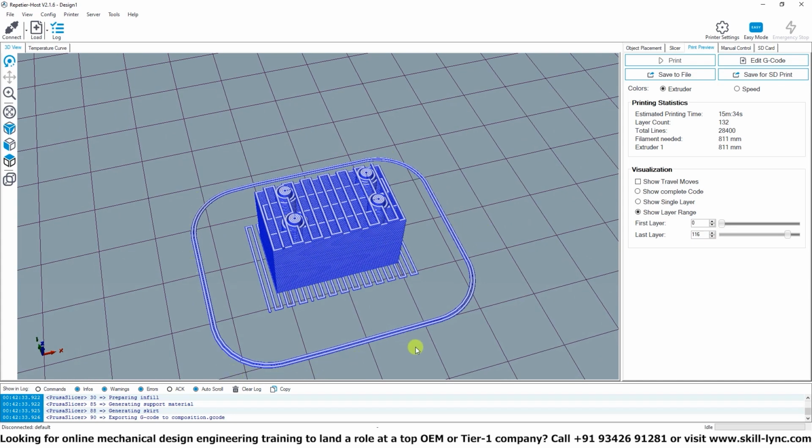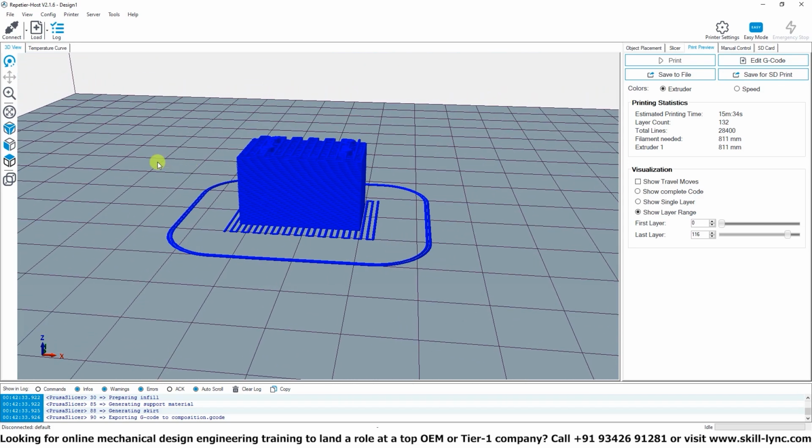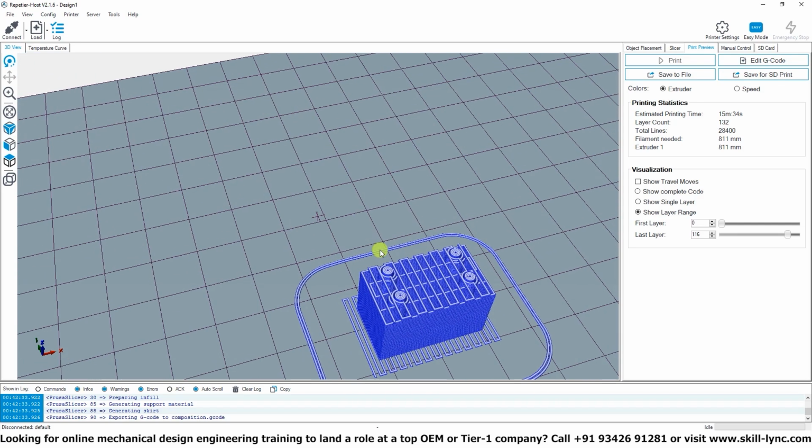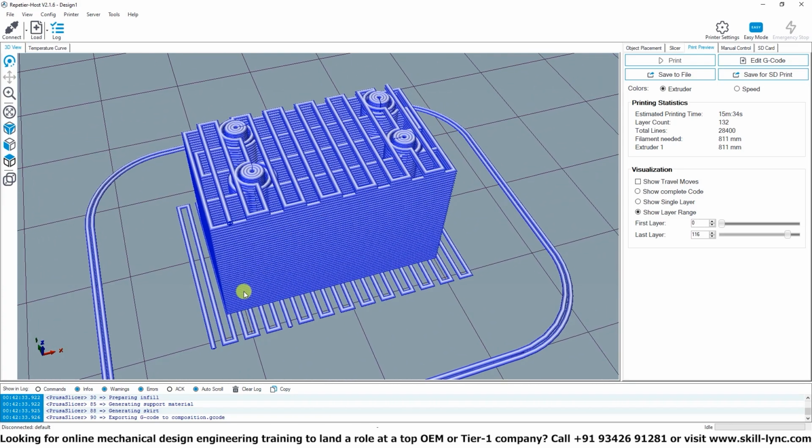This is to clean the nozzle head, and it's another thing that you can set. Sometimes if you are using a multiple nozzle extruder, you'd have an extrusion tower to purge the nozzle between filament changes. There's many different things that you can play around with, but the more you delve into this technology,